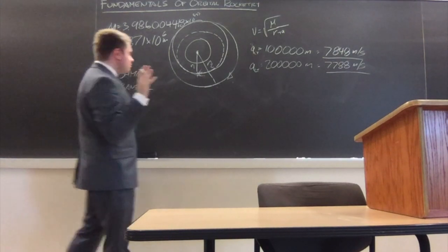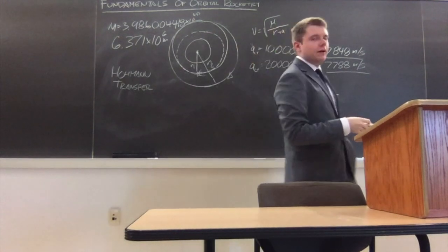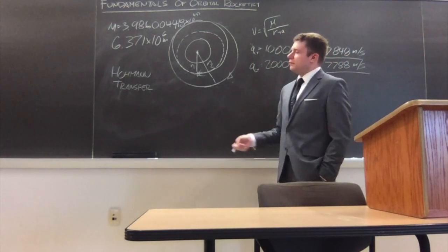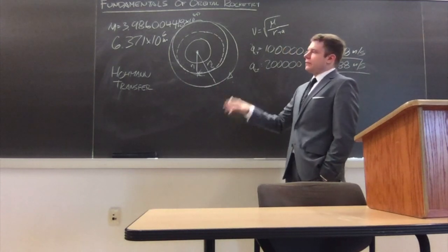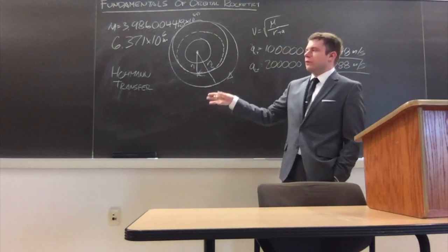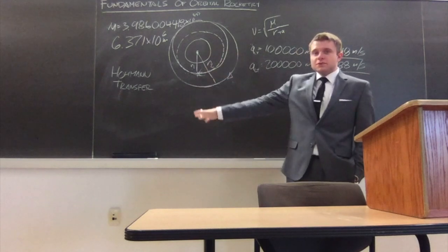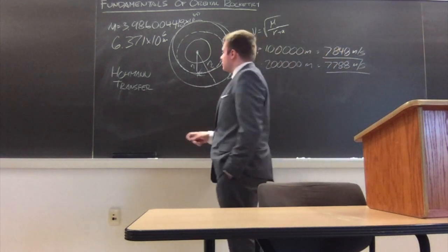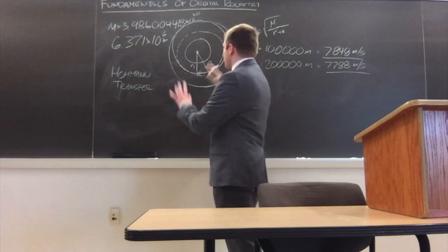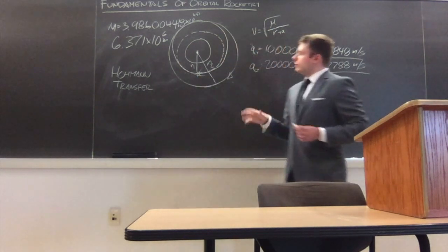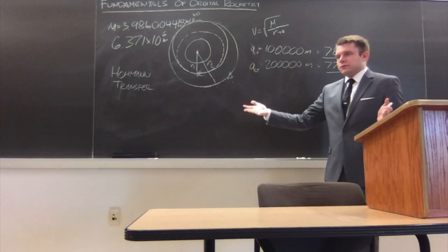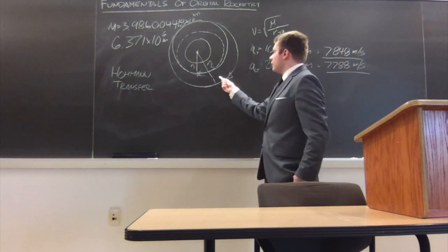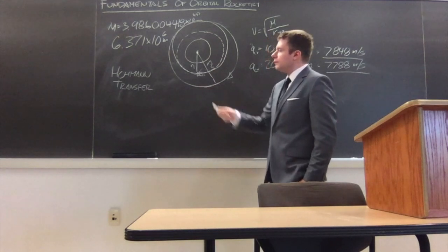It's a very straightforward and direct way of doing it, a geometrically very consistent and reliable way, and most rendezvous and most orbital maneuvering is handled through a Hohmann transfer. There are some exceptions. There's always exceptions to every rule, but we'll get into those in the future. For the sake of this argument, we'll just talk purely about a Hohmann transfer. What a Hohmann transfer does is it connects two orbits, one lower and one higher. You have a target in the higher altitude and an interceptor at the lower altitude.